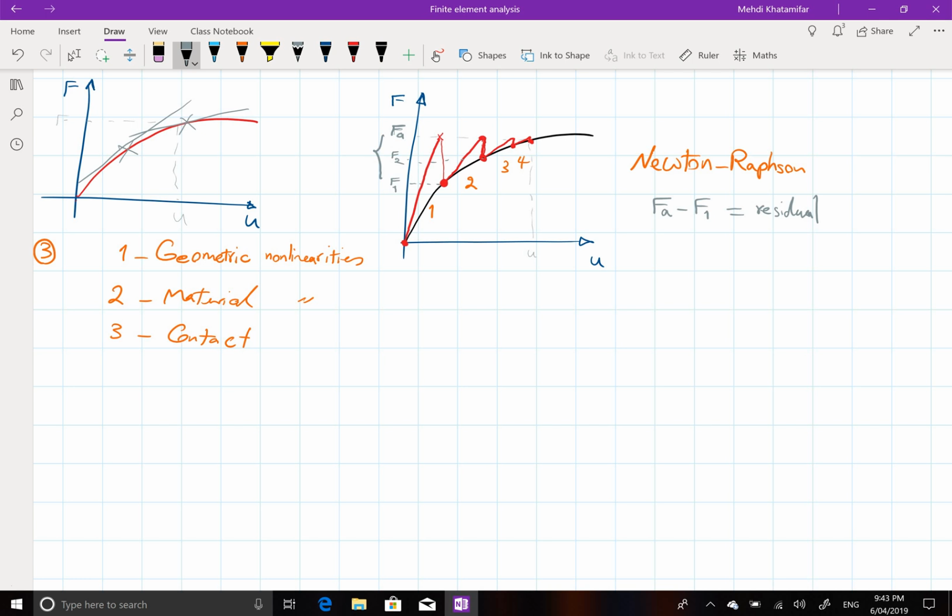For example, we have an option for mesh which is called shape checking. Usually we don't touch it, but if you have a nonlinear model and it diverges all the time and you did everything, you need to change this option to aggressive.